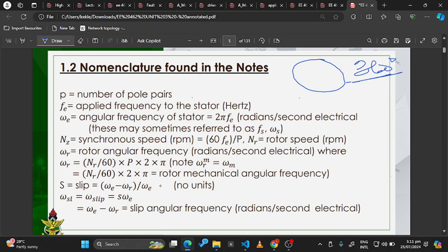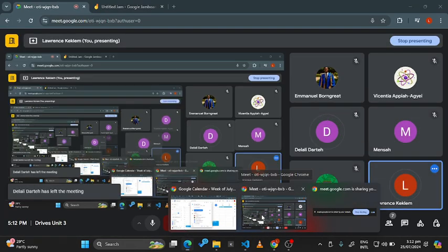But we electrical engineers say that out of 360, we can get even 1080 degrees. How does this happen? If I have a motor, depending on the number of poles I have in the motor, I can have more than 360 degrees in the motor. From asynchronous machines, you know that the poles are placed one pole pitch away. Let me use this to explain.